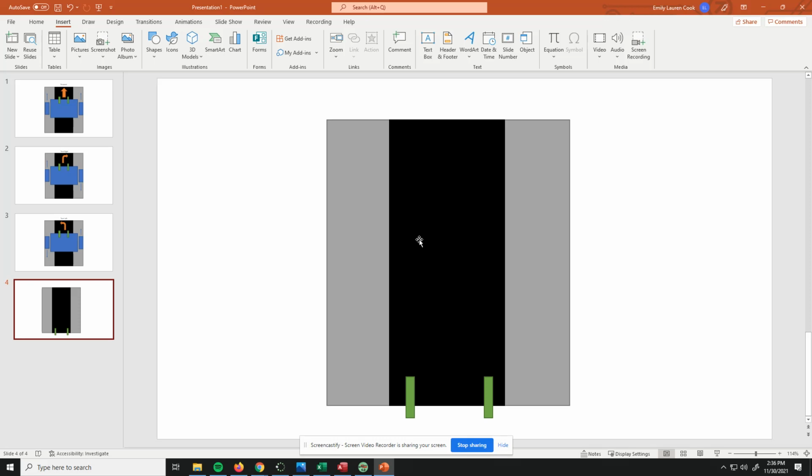And so, what you want to do if you're planning on using the line follower is you want to organize your line follower. So, those little green rectangles, those are your line followers. But you want to make sure that both line followers hit the black tape. And the reason for that is so that the robot, as you program it, understands what forward is. Because it can't go forward if it doesn't know where the left and the right side of the tape is located. So that's kind of the thought process behind organizing your line followers.